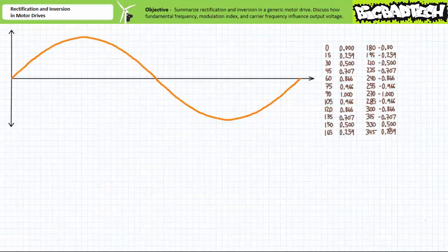First, you have to think of PWM in terms of average values for particular sections of a complete AC cycle. For example, if we chopped up an AC waveform with a period of 16.7 milliseconds, a period corresponding to a frequency of 60 Hz, into 24 different sections, each encompassing 15 degrees of a 360-degree cycle, each section could be considered as having a median value representative of that section.